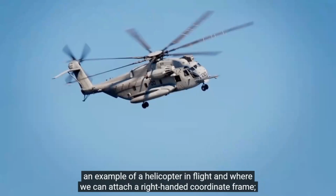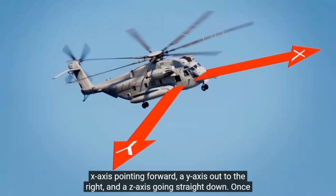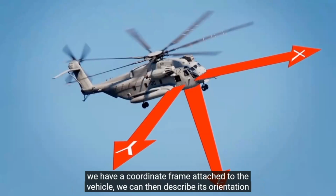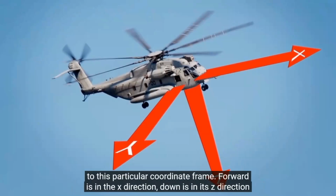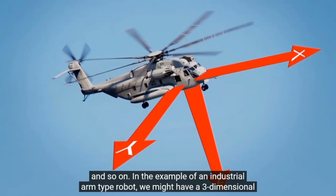So here's an example of a helicopter in flight, and we can attach a right-handed coordinate frame, x-axis pointing forwards, a y-axis out to the right, and a z-axis going straight down. Once we have a coordinate frame attached to the vehicle, we can then describe its orientation with respect to another coordinate frame. We can also describe its motion with respect to this particular coordinate frame. Forward is in the x direction, down is in its z direction, and so on.